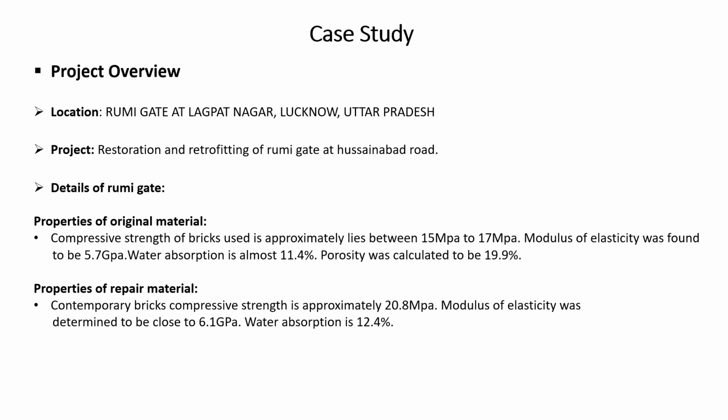Compressive strength of the brick used approximately lies between 15 MPa and 17 MPa. Modulus of elasticity was found to be 5.7 GPa. Water absorption is almost 11.4%. Porosity was calculated to be 19.9%.